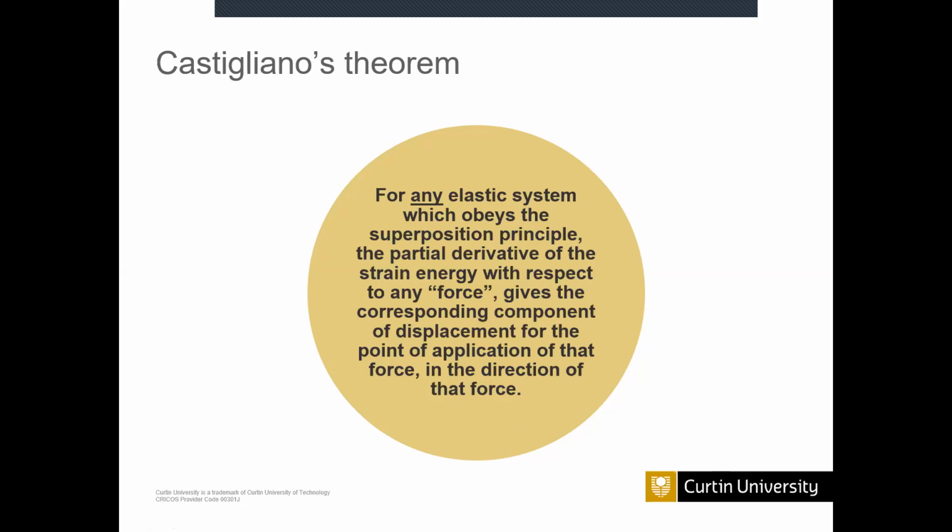Each individual thing, you can calculate separately. That means those individual things should be independent. If it is dependent, you can't calculate those things separately. For example, assume there is a 3rd load. The 2 loads are independent, but the other one depends on those 2. Then you can't use the superposition principle. So the loading conditions and other things should be independent. That's the meaning of the superposition principle you can apply.